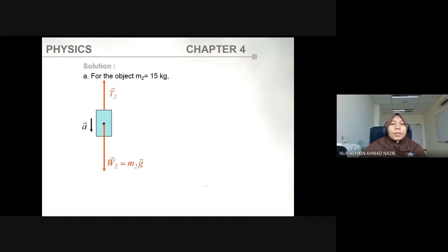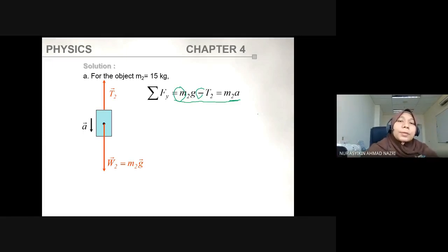Okay, so we have this free body diagram. From the free body diagram, it is upward minus the downward, but this time again, as I said, it follows the direction the same as the acceleration as positive. Do you see this? It takes positive for the direction of acceleration and negative for the opposite direction. But what I usually do is T2 minus M2g equal to negative Ma.